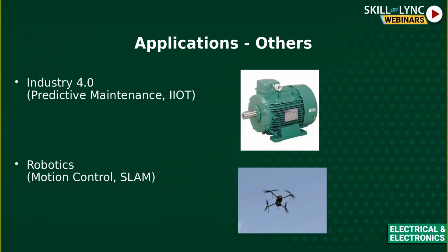And on top of this, you can actually attach a motion detection or a vibration sensor on the body of this. So it's completely non-intrusive. And these sensors mounted on the body can measure the vibration or sound that the motors make. And based on signal processing done on these sound signals, there are algorithms now which can predict when the machine is about to fail, right? So this has a lot of economic advantages by reducing the downtimes caused by unexpected failures of the machine. So it helps in maintaining the machinery effectively and more efficiently.